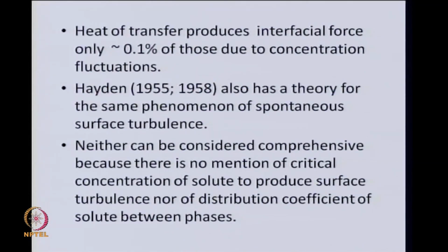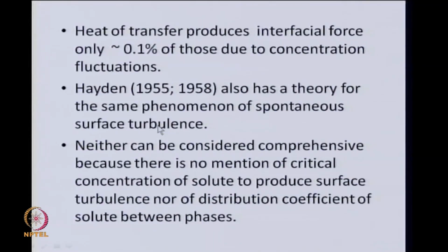Now, one question which may come to your mind is, what kind of interfacial force will be produced if there is a heat of transfer coming into the picture. We did talk about the cooling that occurs of the liquid due to evaporation, but how much interfacial force can be created? Compared to concentration fluctuations, this is negligible, just about 0.1% of what you can achieve from concentration fluctuations. So, as a result of transfer of the solute, whatever cooling might occur is not going to be a very important factor.